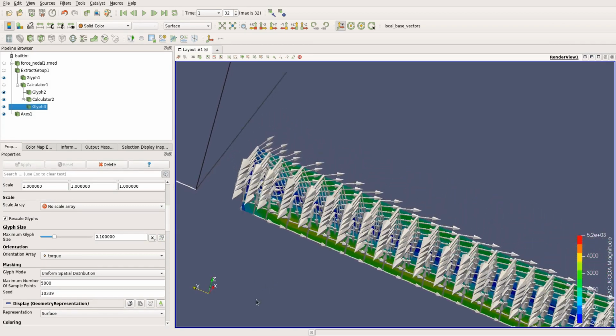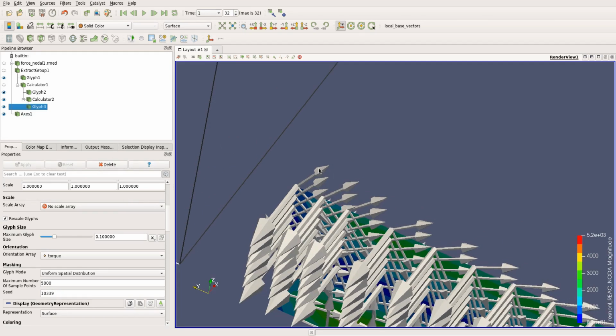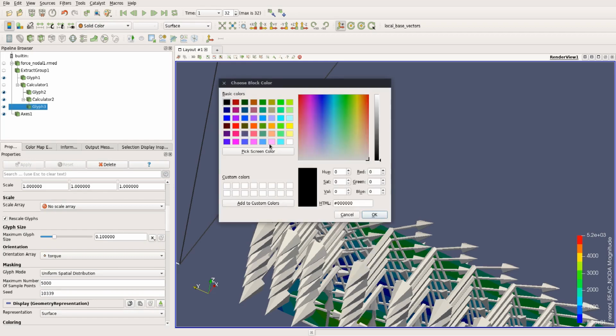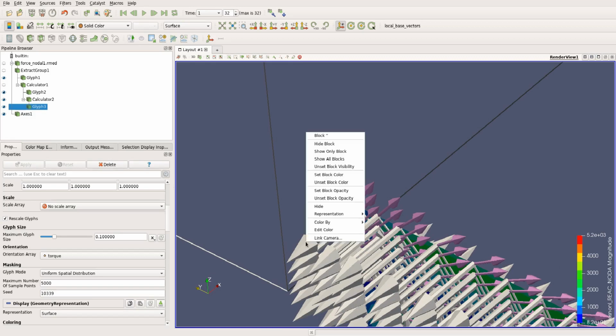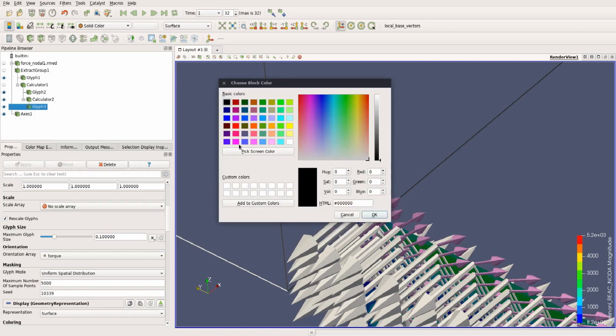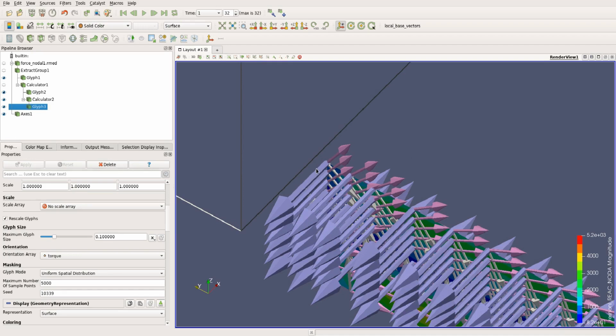so let's focus on this point, my first point. So this is my position vector. Just change their color. Okay, yeah, so the pink is the position vector, and this white arrow now is my, I don't know, let's say purple. Okay, now my nodal reaction is along minus x. So if I look down here, so r cross f, this is my r and this is my f. So if I applied my right hand thumb rule like this, my torque vector should be along this direction that I just drew.